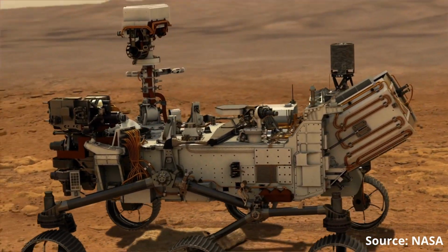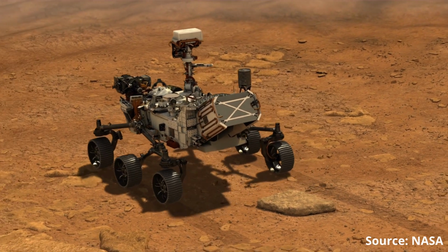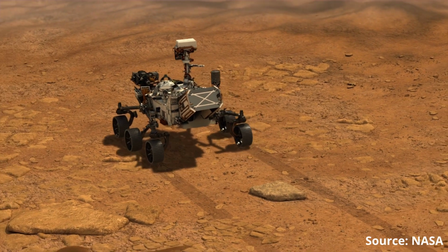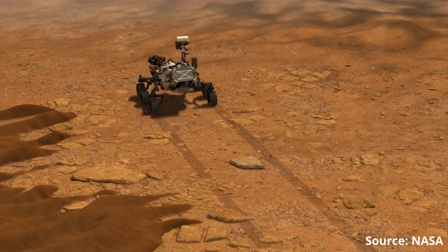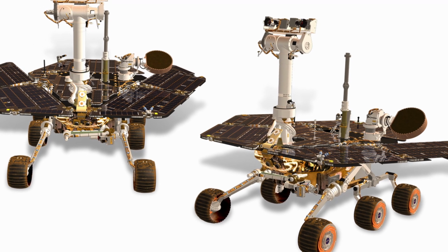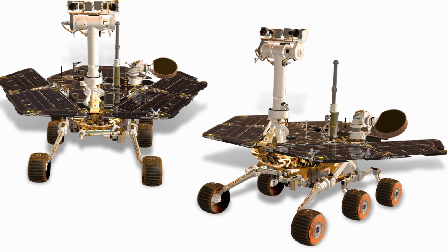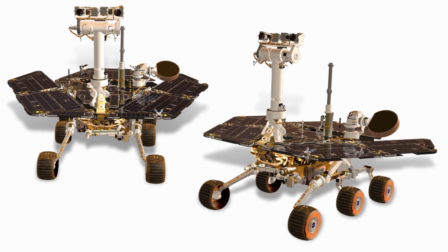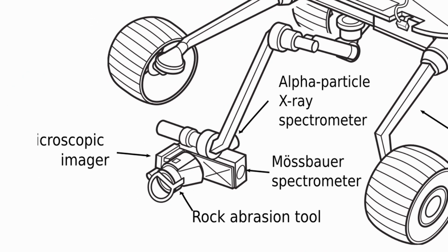On most planetary surfaces, we face the problem that the rocks we want to inspect are typically covered in dust. A corer or grinder can be used to expose a fresh surface for measurements by abrasion. NASA's twin Mars exploration rover Spirit and Opportunity both implemented a grinding tool in the so-called instrument deployment device. The instrument deployment device was the end effector of the 5 degree of freedom robotic arm.